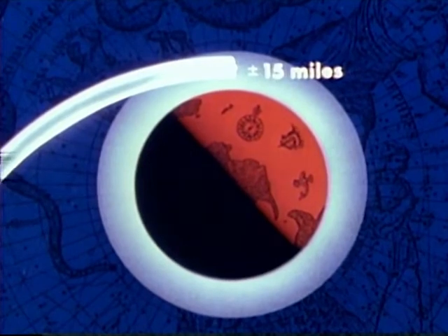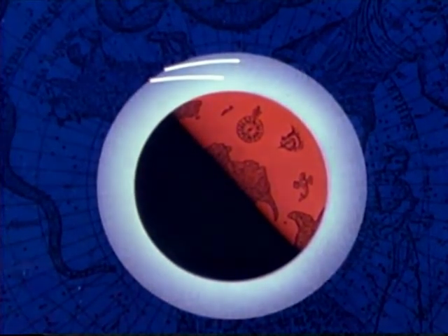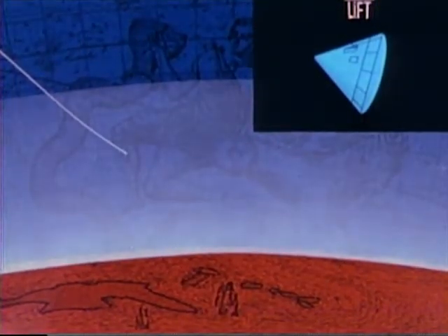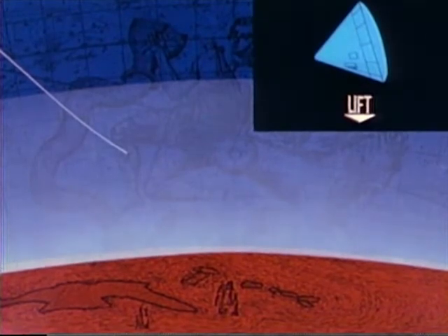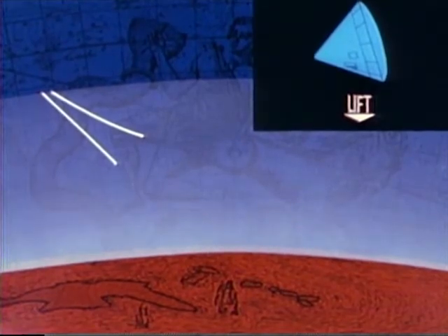We have seen what defines the entry corridor with its overshoot and undershoot limits, how aerodynamic control of the command module is achieved by rolling it around its offset center of gravity, thus changing the direction of lift, and how this increases the depth of the entry corridor. We are now ready to see what happens to the command module during the entry phase.